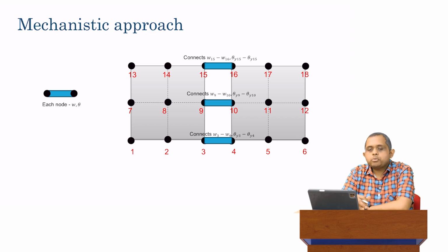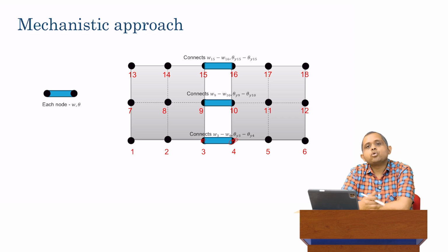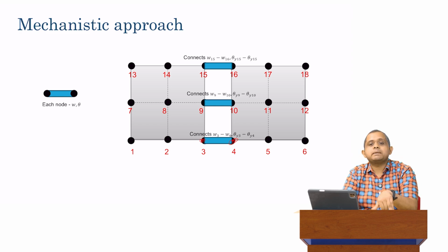Okay, so here is an illustration of what I just said. So again, our toy problem, which is this 2 slab, each slab consists of 4 elements. Now, previously what we were seeing is we were connecting W3 and W4 with a spring element. So we were saying there is no interaction between the rotation elements, the interaction is purely among the displacement elements. Now what we are seeing is that we are going to model the interaction between node 3 and node 4 using an Euler-Bernoulli beam.